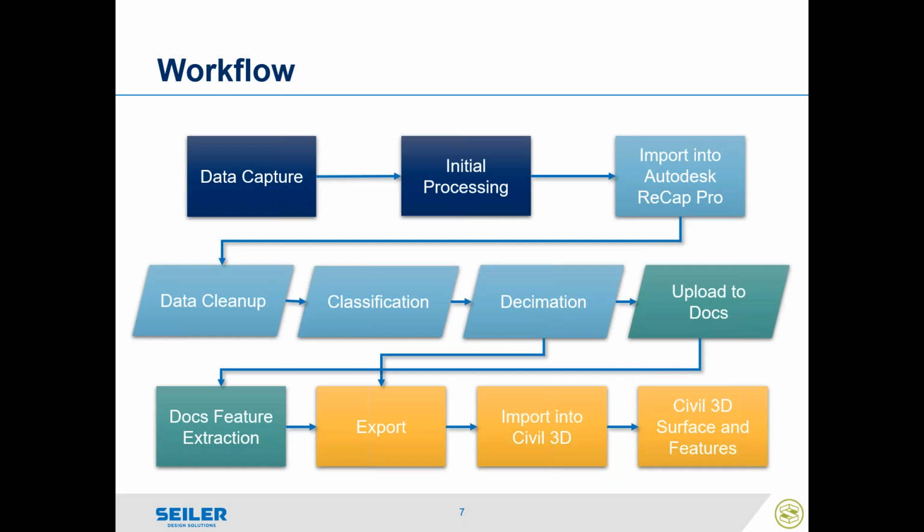They're using AI to help assist with this data extraction of curb lines and sidewalk lines, and help you place points properly inside your drawing or point cloud model to pull that out. And we can export that data as either LandXML or DXF file, or points as a CSV file to dump into Civil 3D to create our model. Okay, so that's what we're going to run through with this.